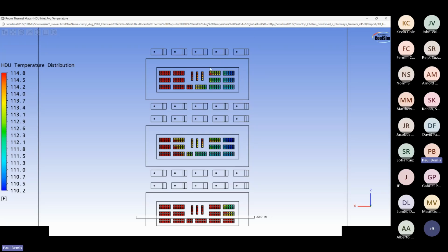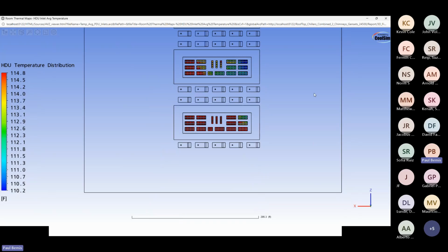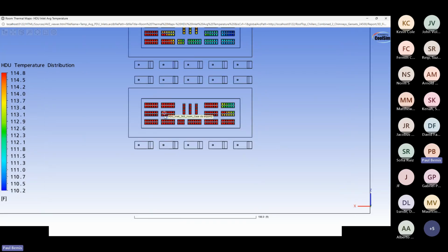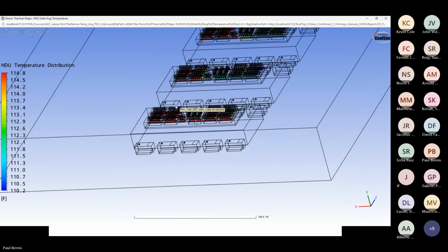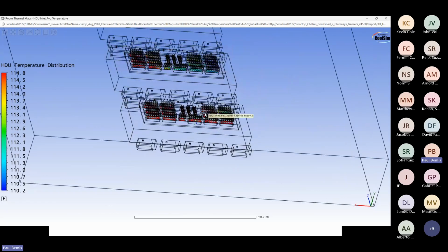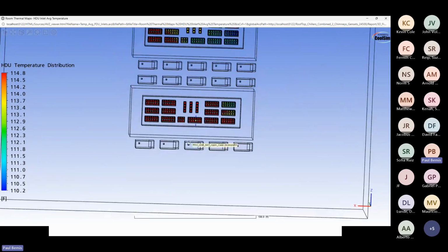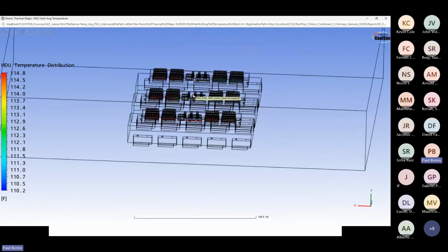The wind is coming from this direction, so I'm getting recirculation on these devices. And it's always the most downwind one. It's this one that's got the worst situation. So it's seeing about a 5 degree rise in inlet temps down there. Still not too bad. So in this case, under this run, I'd say yeah, we're probably okay. This will probably be fine running it in this configuration.